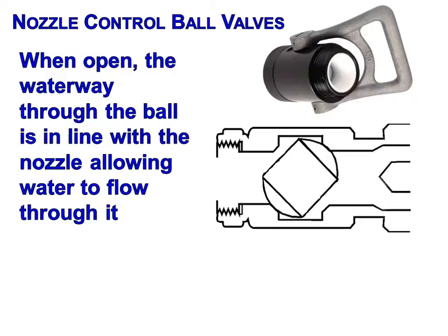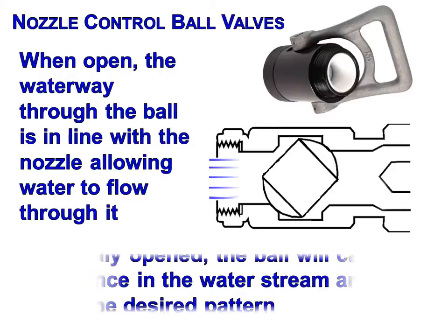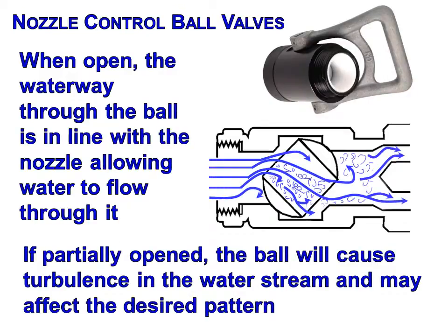If partially open, the ball will create disturbance in the water stream and may affect the desired pattern. So it's either you open it all the way or you close it. If you only open it halfway, you're really not going to get the reach or the GPMs that you're wanting out of that. As you can see there.